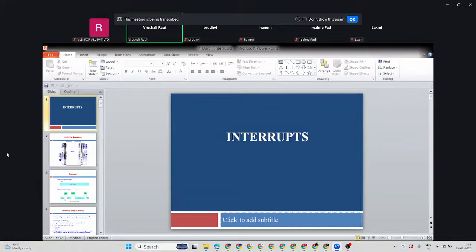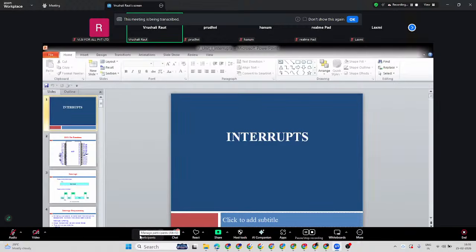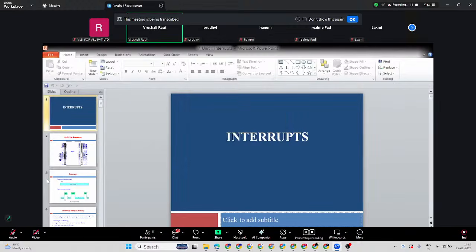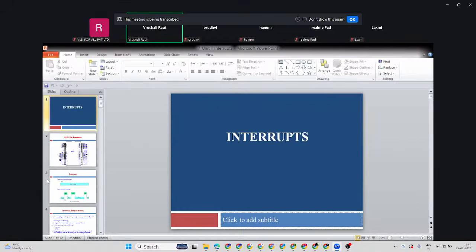Okay, so it is like its name only, interrupting the main program, but depending on the priority set by us. So those interrupts we are going to check. Very clearly, I'm putting this pin diagram in front of you because I want to show you that INT0 and INT1, actually they are INT0 bar and INT1 bar. These are the external interrupts which are there in 8051.